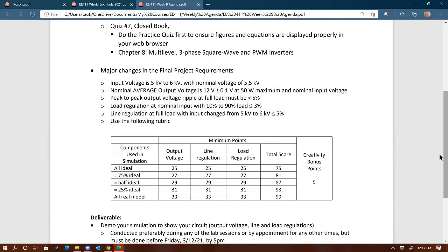The same thing: the DC system is high voltage, maybe around 400 to 600 volts, going to very low voltage again to keep the cabling size and the wires tiny. Because if you can boost the voltage, then for the same amount of watts, the current is small. That's how you would reduce the size of the wiring. Therefore, you can come up with a more compact and lighter electrical system.